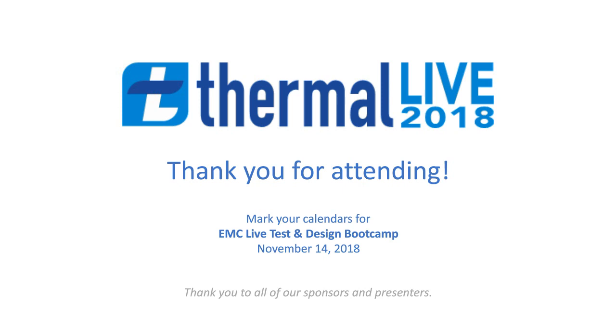We have a number of questions that have come in, so let's get right to them. First question from the audience: do PCMs suffer from aging? What are the material characteristics that deteriorate? So this depends on the PCM. Organic paraffins, especially pure components, typically do not suffer from aging problems. We have them currently in products that are meant to last for up to 30 years.